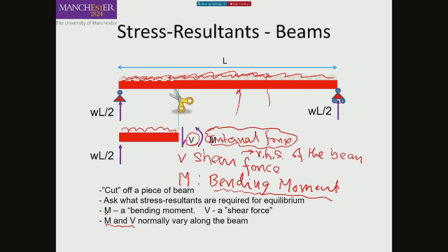So it's essential in design. If you are given a set of loads and a span of beam, that's what you do. First find out the bending moment and shear force along the length of the beam. Pick up the maximum location, find the stresses, and compare that with the material behavior. That's probably slightly further down the line. We'll definitely revisit how to do design, but that's the context. Why do I need to know about these internal forces? Because those internal forces will give rise to stresses, and that's what we need to compare with our knowledge of the material property that the beam is made of.